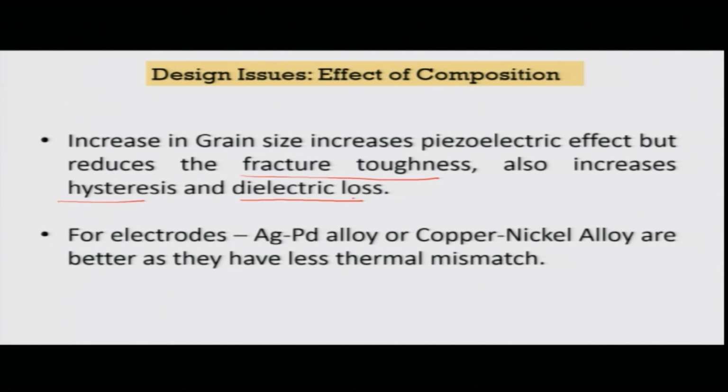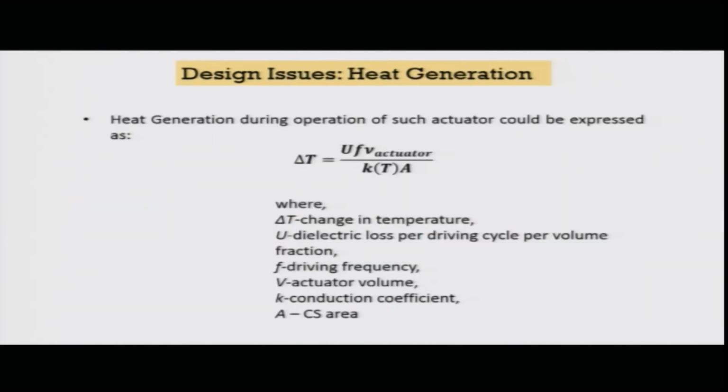So, you have to think of the optimum grain size that you can go for, and the electrode variation also. For example, you can use a silver and palladium alloy, or a copper nickel alloy system, and you would see that these systems are better as they have less thermal mismatch, because temperature would also be an issue in the design of such a system.